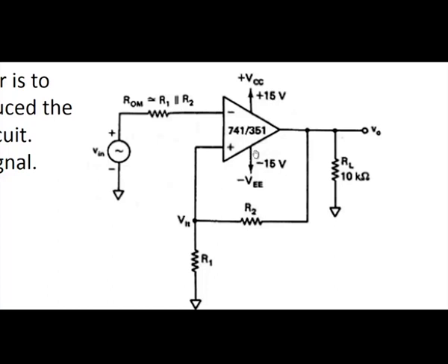So, it is a positive feedback. If positive feedback is given, then the gain is increased. If the gain is increased, then whenever the input voltage crosses the V reference voltage, the output will transition instantaneously, as the input exceeds the limits present at the positive terminal. Because of this positive feedback, this circuit will also have hysteresis. We will see the hysteresis deeply.